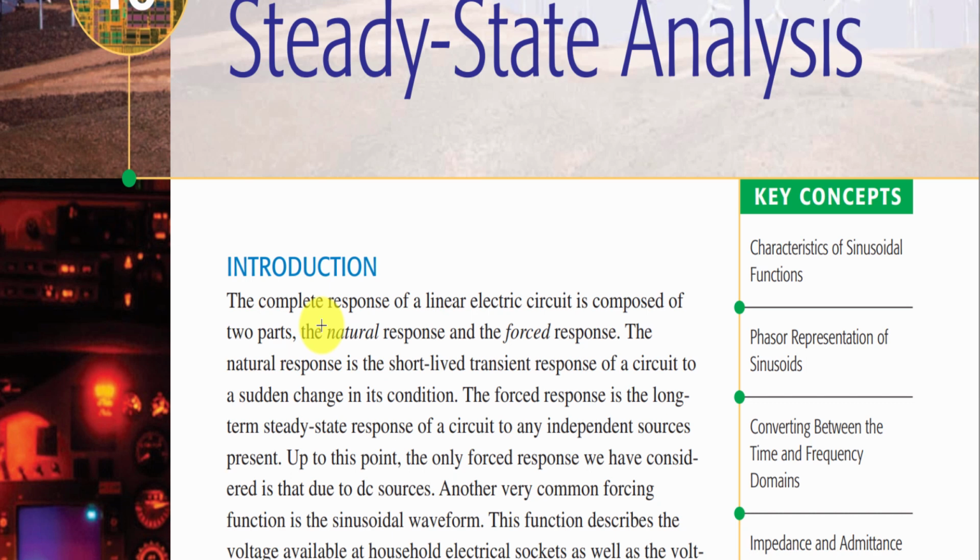You might have noticed that whenever you turn on a heavy inductive load in your house, such as the motor for the water pump or the air conditioner, the lights flicker for a few seconds, and then everything gets back to normal, because the electromagnetic field requires a large amount of current to build up in that inductive load.